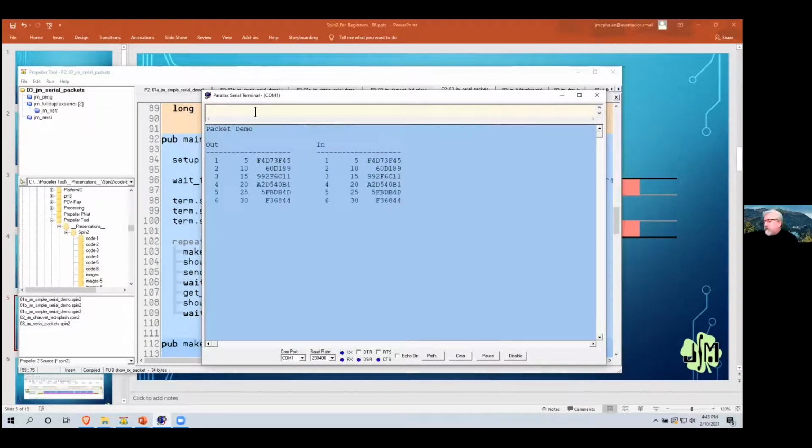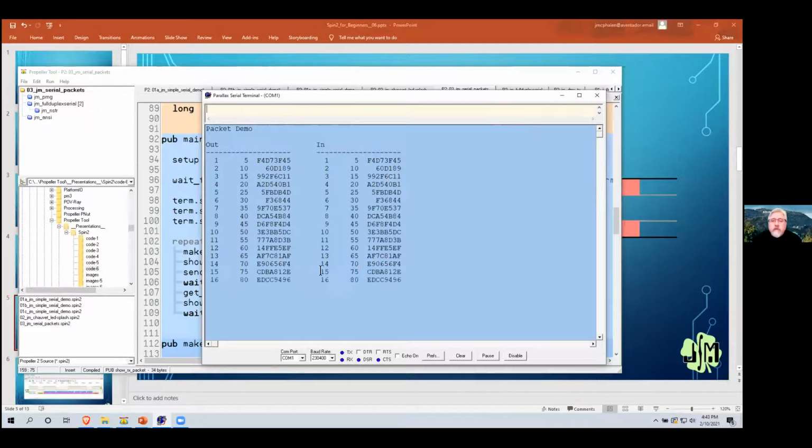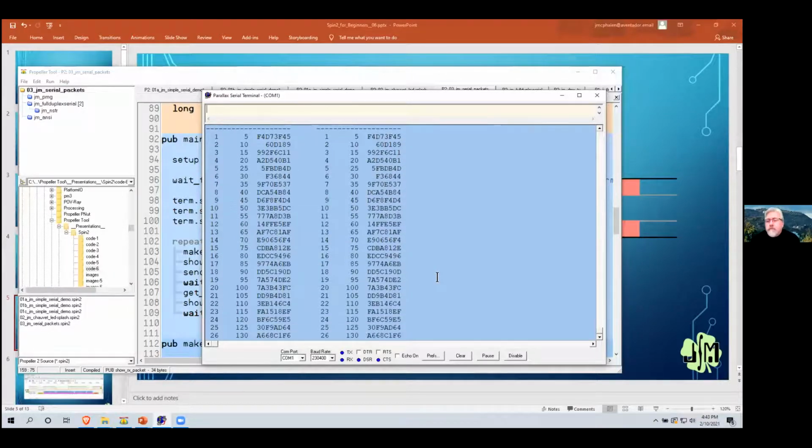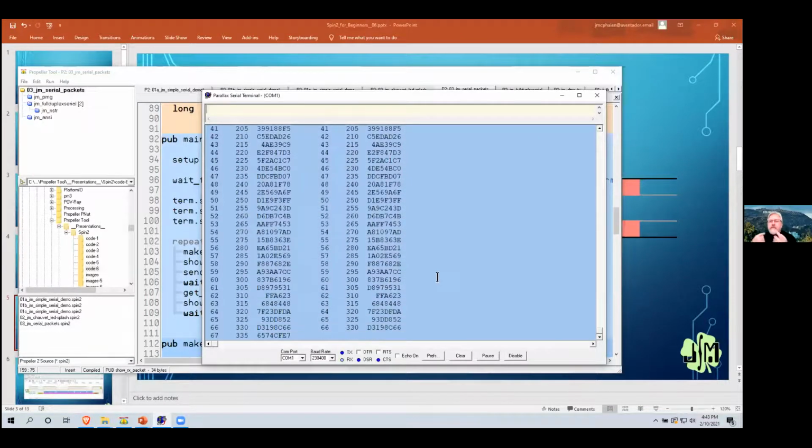And so, you know, this is nothing terribly exciting. You can see this is what's going out. And if we look, we get the same thing back in. This is just going through a little tiny wire. But once I had this kind of idea working between the 2 boxes in John's system, then we said, okay, we have messages going back and forth. In that particular case, we actually had a command message that went out and then a response message that came back. So we had transmit and receive in 1 30 millisecond frame.